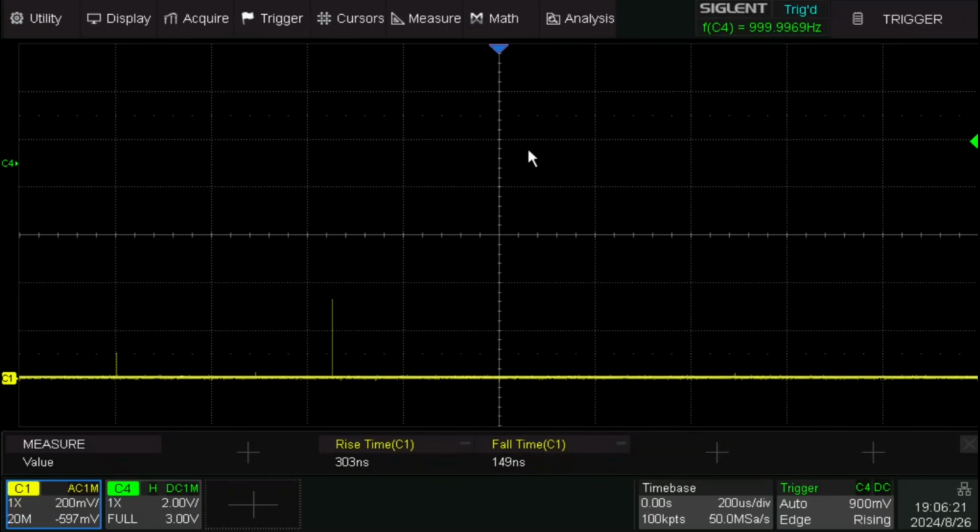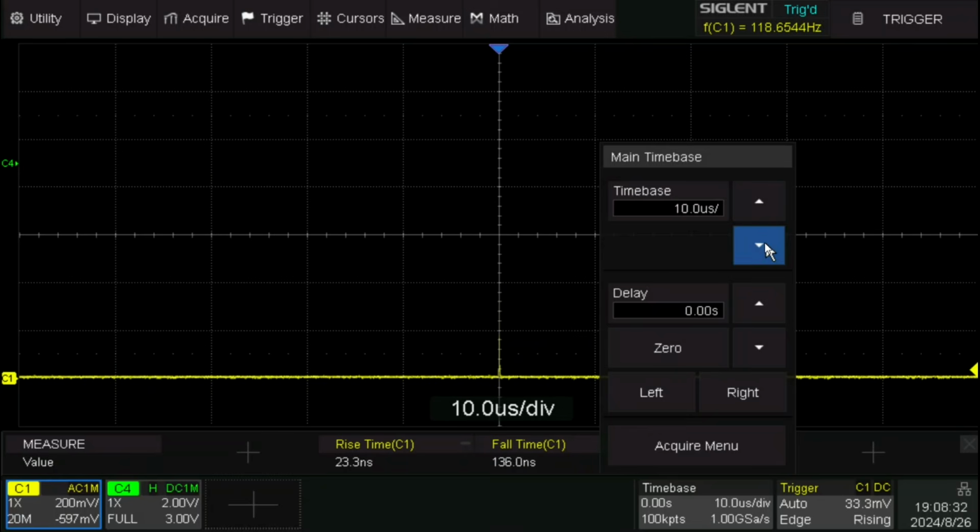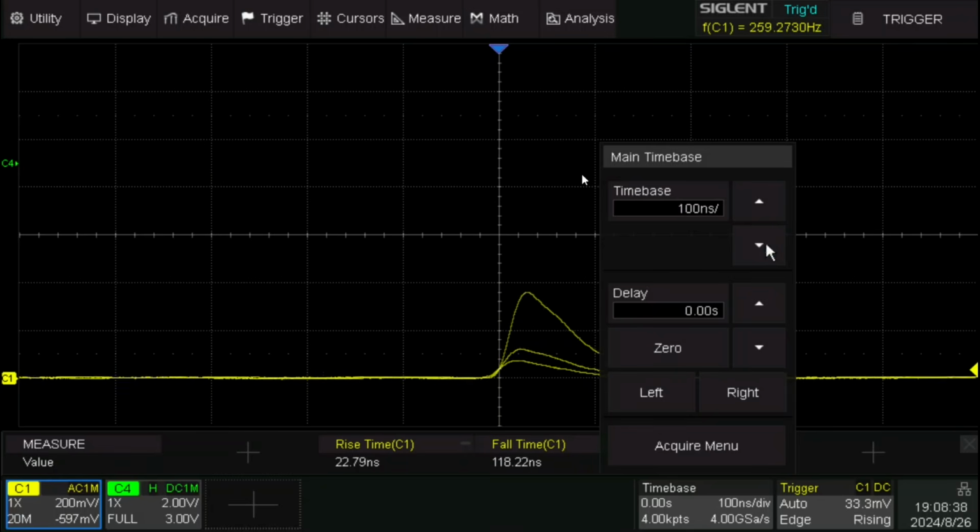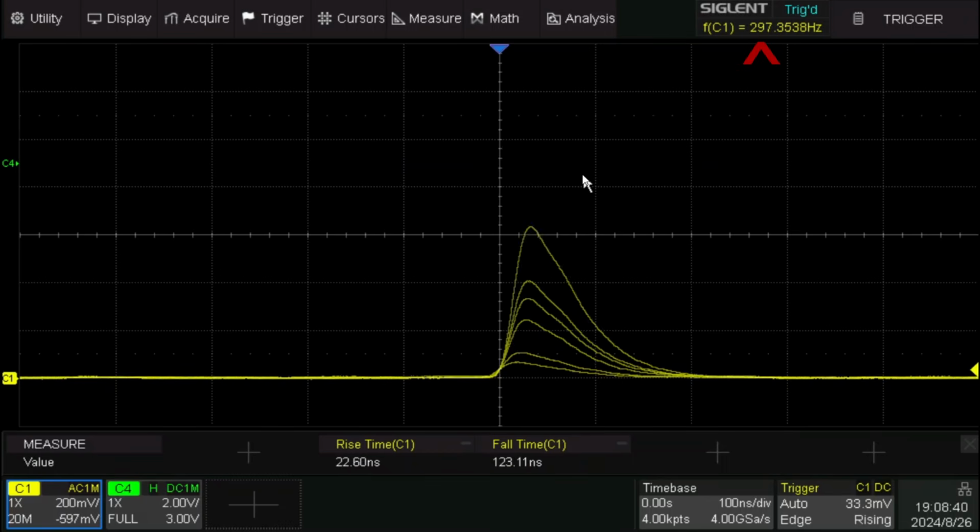But where do these spikes come from? Because, as just stated, the device is now in complete darkness, and it turns out that additional measures to further darken the room or the box have no effect. These pulses remain present. As you can see, there's actually quite a lot of them, and if we trigger the oscilloscope on these pulses, we measure on average about 300 per second.